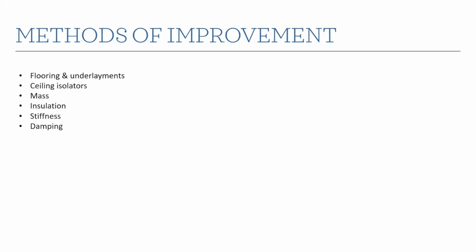acoustical engineer. Damping is another thing, and damping can range from something that's fairly simple, like an off-the-shelf constrained layer damped gypsum board product, but it can go all the way up to a tuned mass damper at the top of some big tower, right? And there's all kinds of different ways that we can apply damping. Really, it's like the shocks on your car. It just resists that motion, so it kind of smooths it out.